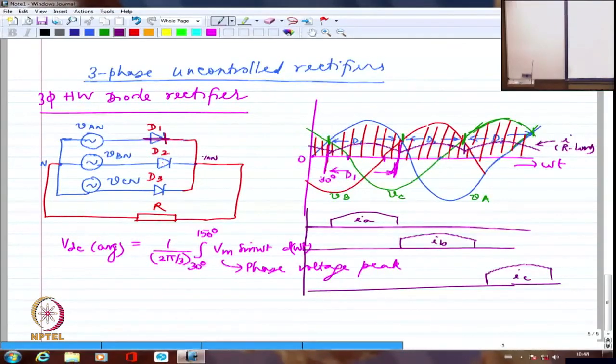And the currents are far from being sinusoidal anyway. So this gives rise to a huge amount of harmonic content, and without any negative half cycle, saturation of the transformer could very well be seen in this kind of rectifier. So this rectifier is really problematic because of these reasons.